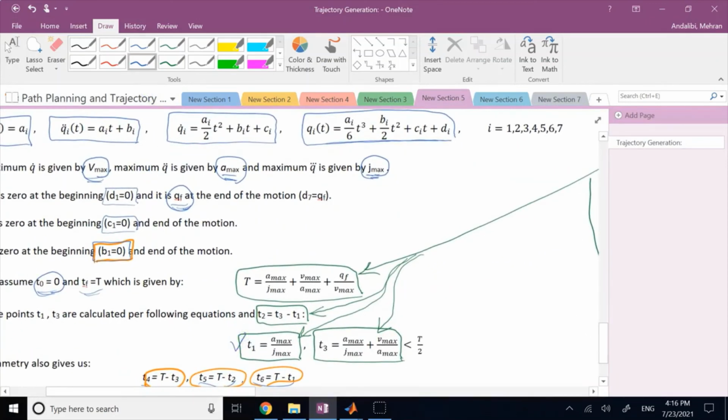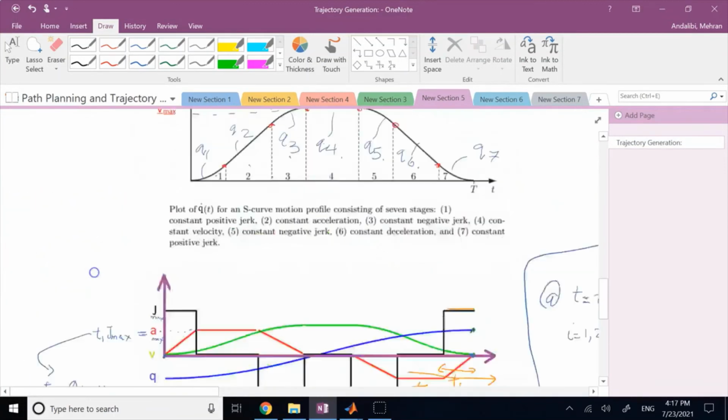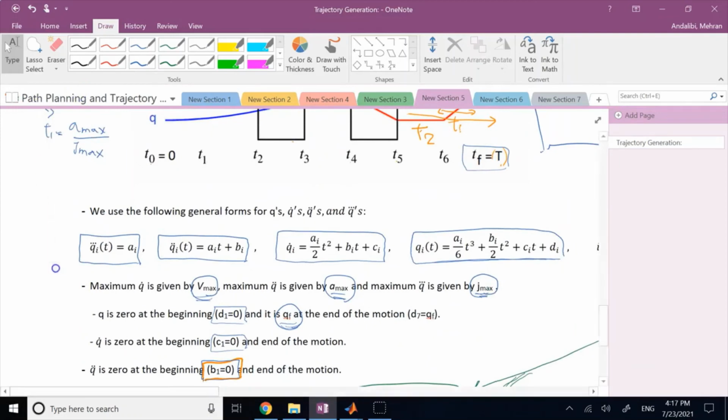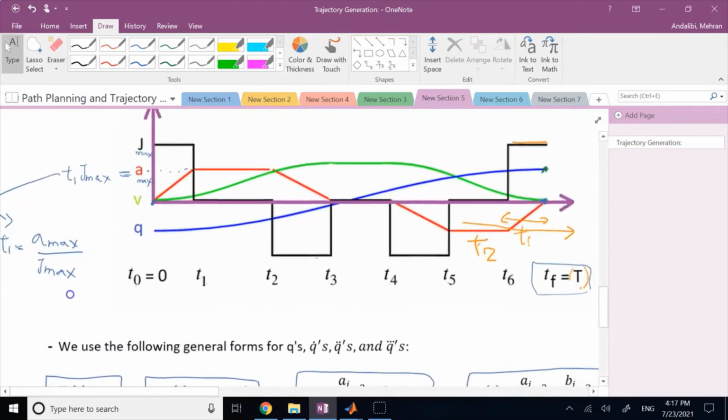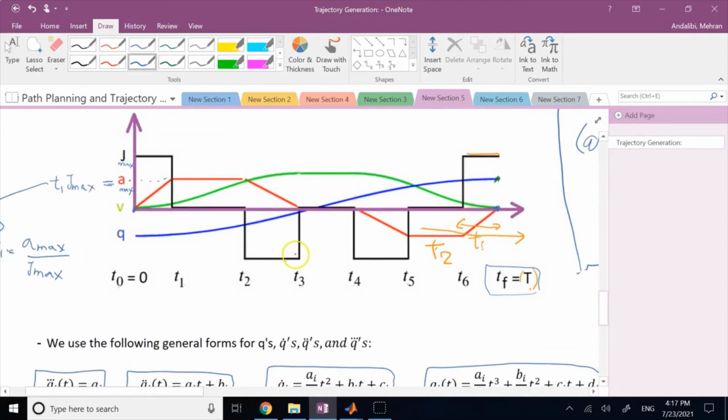Right? Where does the other formula come from? T3, for example. T3 comes from what? Well, for T3, let's go take a look. T3 is the end of the third part, where you go through one full trapezoid of acceleration. During this full trapezoid, which goes from 0 to T3, you go from 0 speed to what? To the Vmax speed.